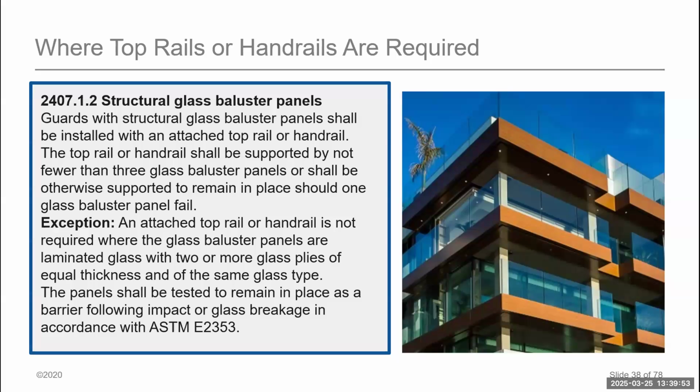What that means is basically the glass will deflect and create an opening in that glass, which, if my hand was in there, could create a pinch hazard. So when we have a system with 9/16 glass, because of the pinch hazard, we do need a top rail. It's at 11/16 and higher that we will typically see systems without a top rail specified.